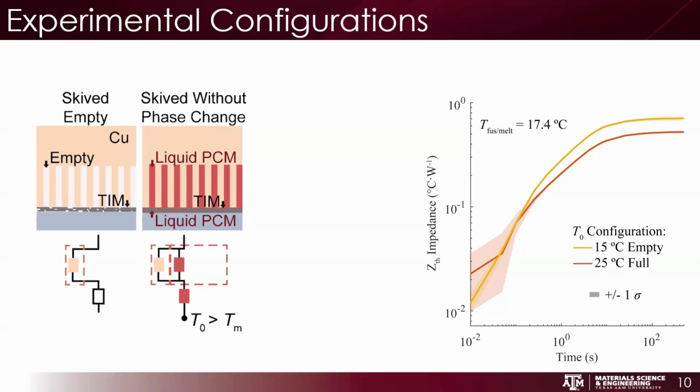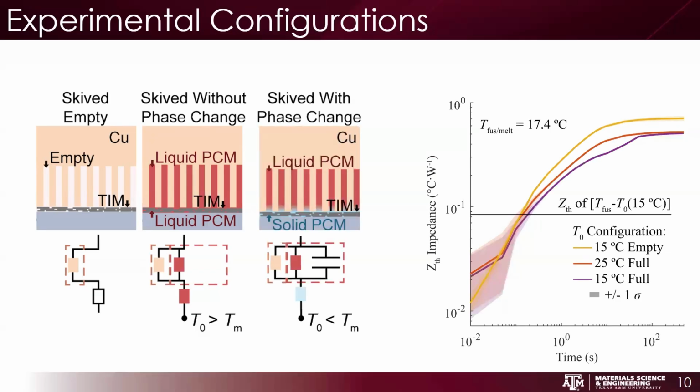that this is at steady state, this would be a better heat sink because the PCM that we're using in this is a paraffin heat wax, which has a higher thermal conductivity than air, which means that it has a lower steady state resistance. And then we can have a phase change happening within the system.